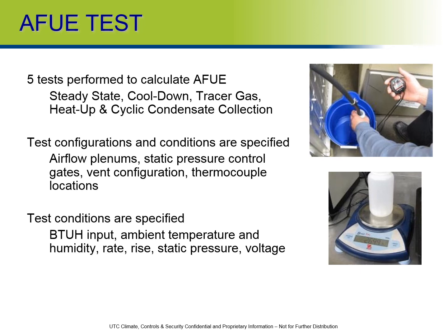They know from their energy provider the exact BTU input in the gas. They know the exact ambient temperature that they're measuring in, and the humidity is pinpointed. The rates, the temperature rise, the static pressure, the voltage, it is all set and specified for their application. So in other words, they are testing in perfect conditions compared to what you're going to be testing against in the field.